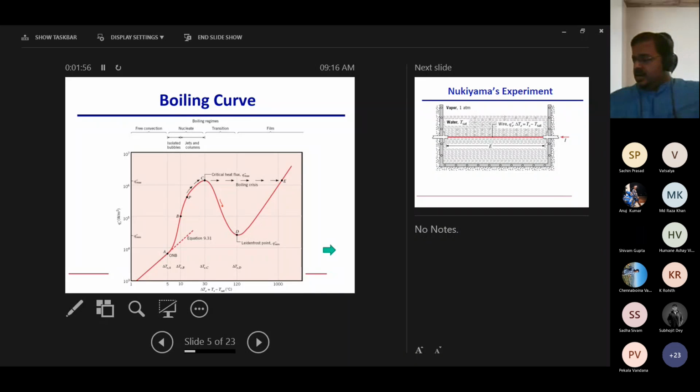Now this point, this Leidenfrost point, what is this point? It is when the entire heater surface is completely covered by the vapor film. Let me give you an example which we have all seen, where the person probably unknowingly uses this phenomenon. Have you seen, and I know several of you are from South India or anywhere, even here also, when they make dosa in the streets, right?